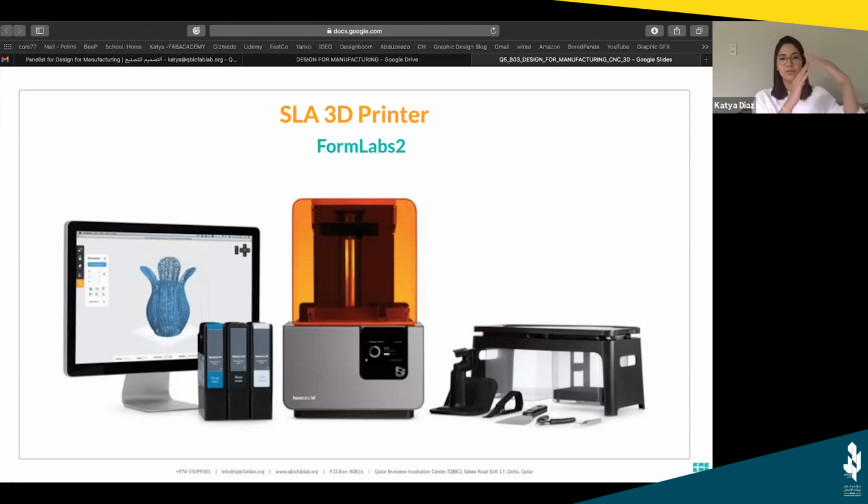So you have to make a support from the table to your print, and then you have to make support in the entire print. As I mentioned, it prints face down, and it cannot print in the air, of course. So all of it needs to have support. What might take, for example, 2 hours in an FDM printer might take up to 5 or 6 on an SLA printer.